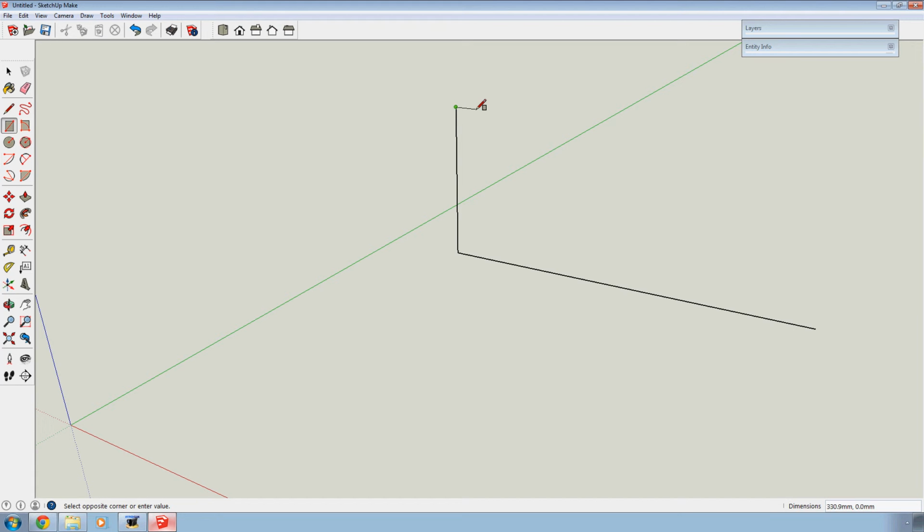If I go up here, now normally when you draw a rectangle with SketchUp, normally it'll try to draw it on a plane which is sort of parallel to the floor. But I'm going to hint to SketchUp what I want it to do by moving down to this line here. And so it's thinking, oh well, maybe what I want is to actually draw it in the vertical plane. I've given it a clue. It's inferring. This is the expression SketchUp themselves use, it's inferring that I want to draw a rectangle from these 2 points. So I'll click on that, and now I've got my rectangle.